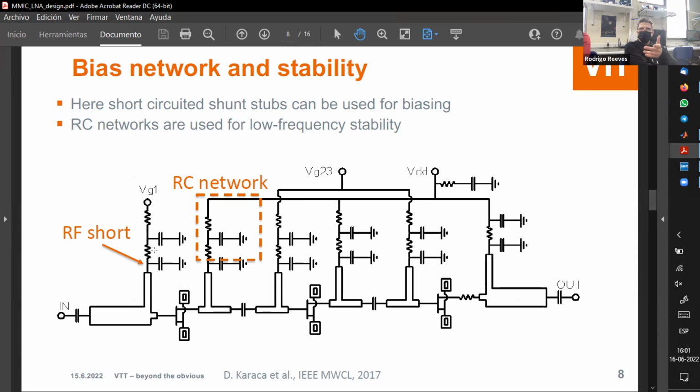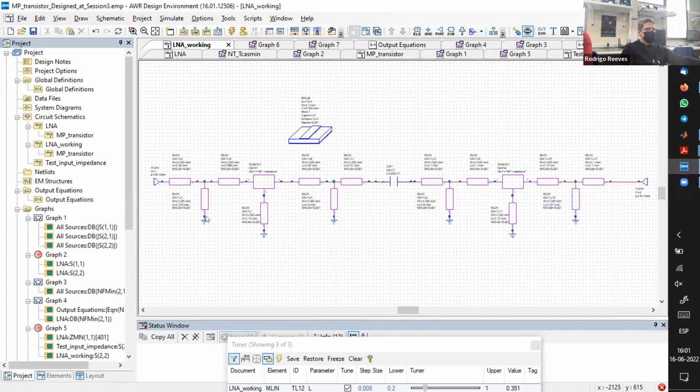So we know that resistance adds noise because it's a lossy component. It's kTB, k times temperature times bandwidth. So it adds noise, and it also cancels the signal. So if you can now add, let's say, 2 picofarad capacitors maybe to that short circuit.